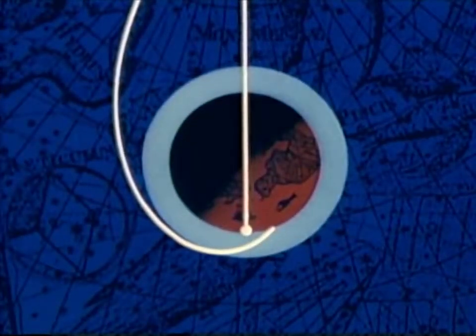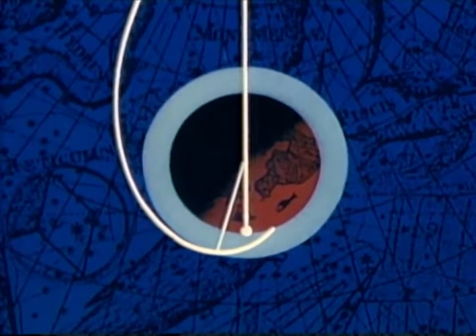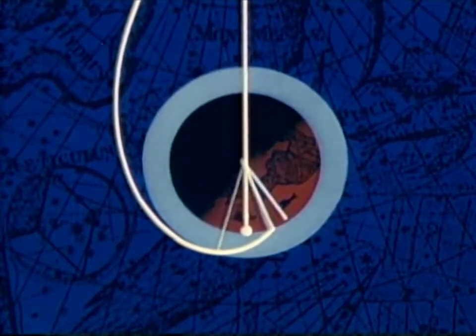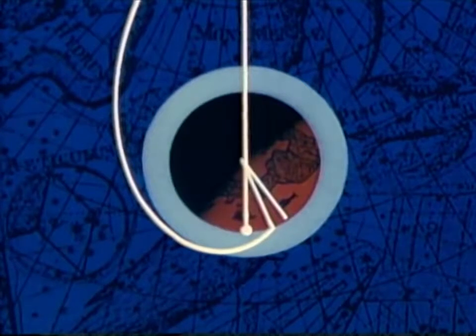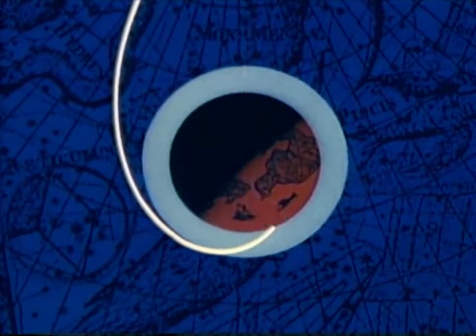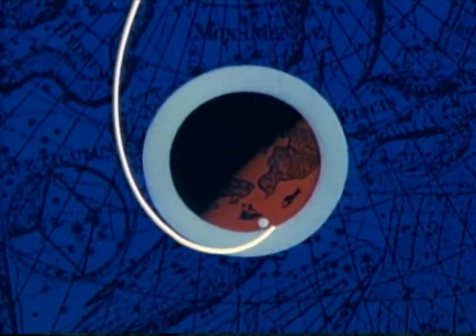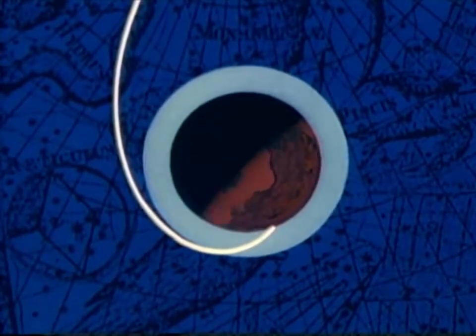The distance from the point of entry into the atmosphere to the antipode is relatively fixed. The entry range limits of the spacecraft are also fixed so that landing occurs near the antipode. Therefore, the landing area is defined, and the target point can be selected within this area. The recovery forces are, of course, located on the surface of the Earth and rotating with it, while the trajectory is fixed.